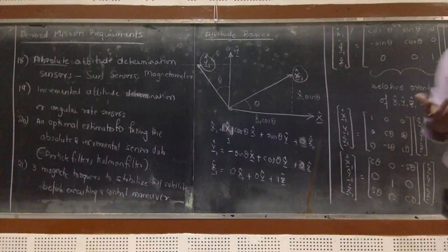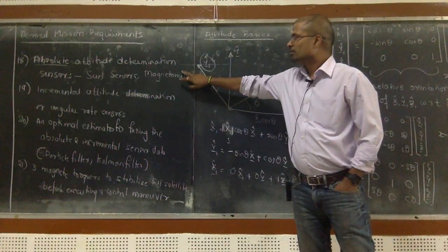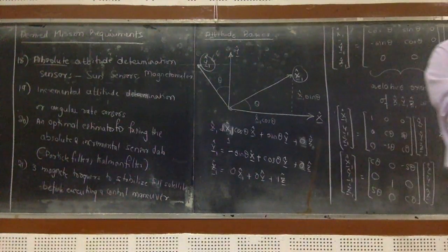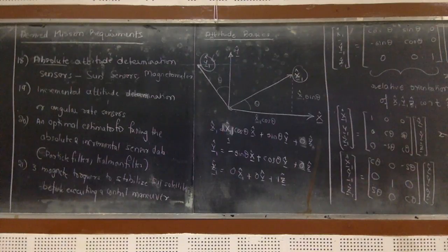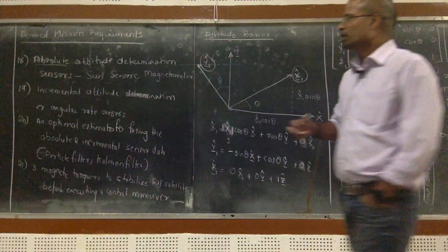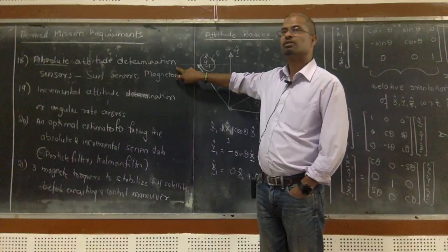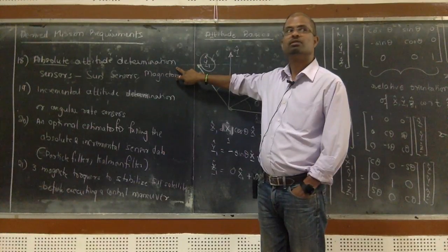Now what you do is, these sensors will have bias, these sensors will have bias. You can use 2 sets of sensors in a filter to account for that bias. One sensor will account for the bias of the other. You have to integrate them, you have to fuse them together to get rid of that bias. And you need something like a filter. So the filter is such that, you realize, can you get angular rate readings from this? No, sir.